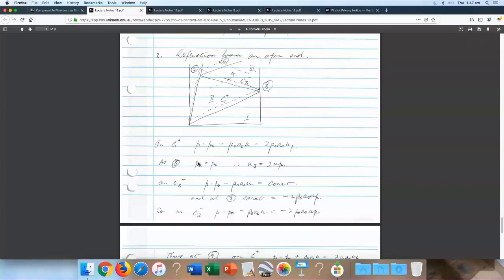What is the internal flux of heat? But even the idea of heat, Fourier's law, Q is minus K dT dy or dT dx. That's a continuum approximation that won't work well if you're talking about distances that are of the order of a couple of mean free paths.